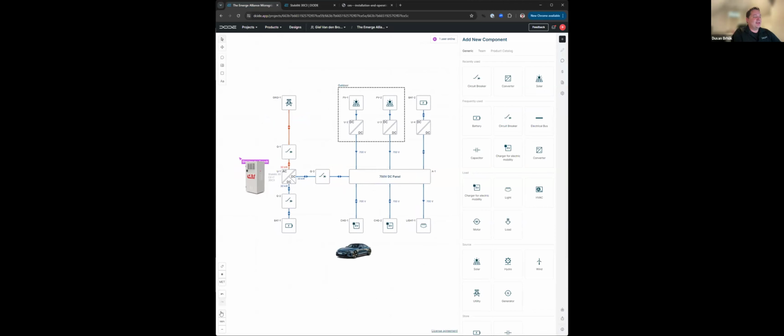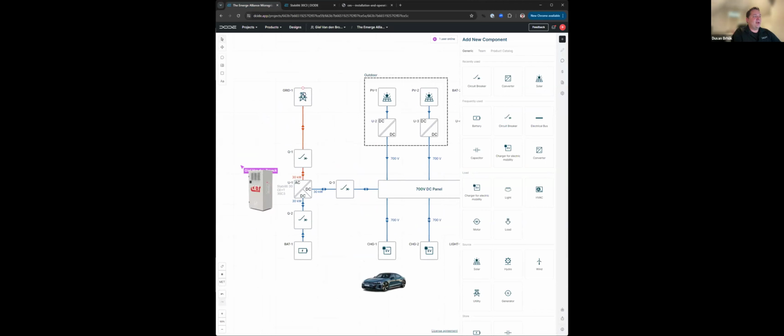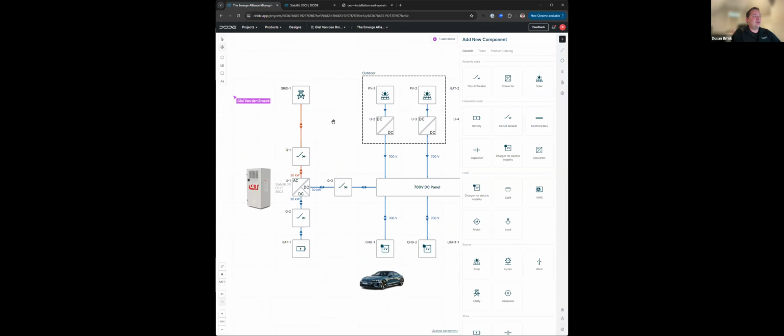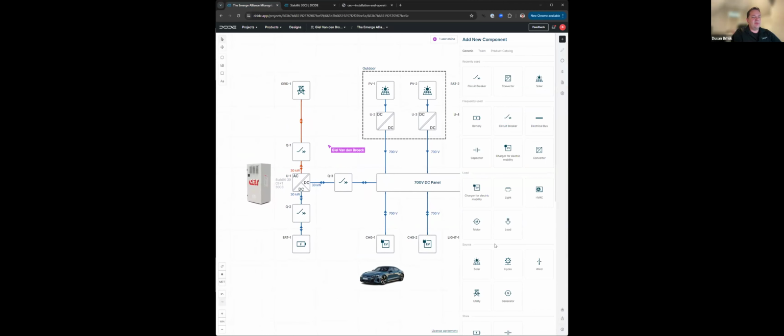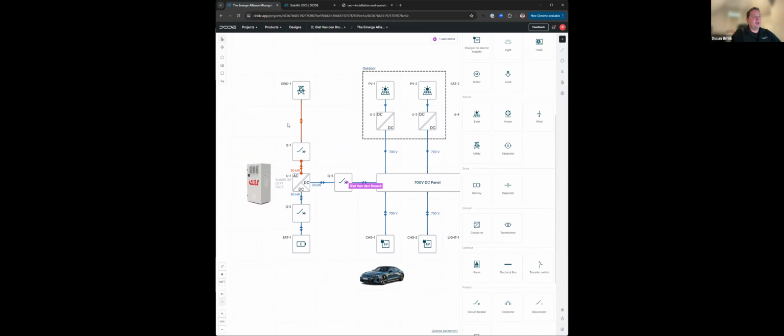And so like you said, this diagram is evolving, and the support of unbalanced loads is really important, I would say, during an islanded phase, not necessarily a grid connected phase. So what I would typically do is move that grid and add a transfer switch. A transfer switch helps you isolate between the utility and the rest of the system.